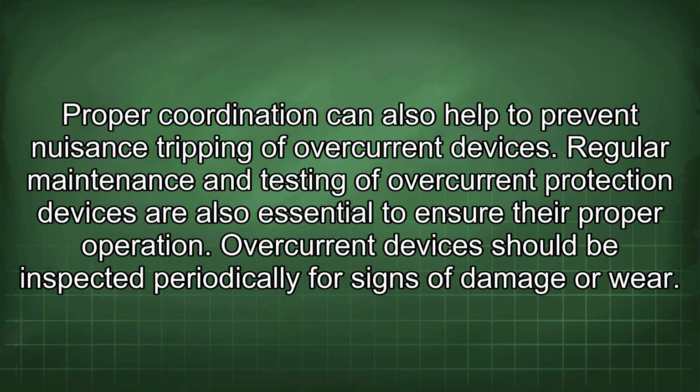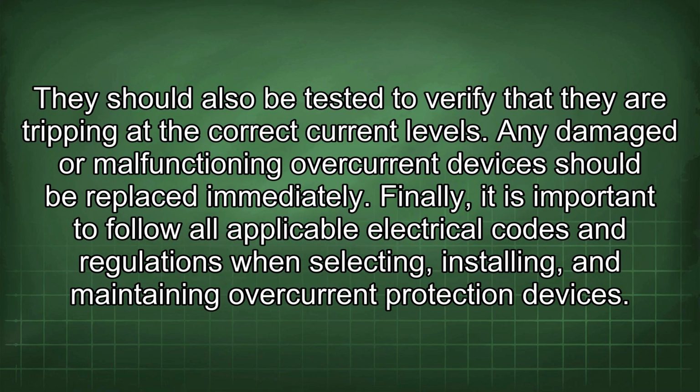Regular maintenance and testing of overcurrent protection devices are also essential to ensure their proper operation. Overcurrent devices should be inspected periodically for signs of damage or wear. They should also be tested to verify that they are tripping at the correct current levels. Any damaged or malfunctioning overcurrent devices should be replaced immediately.